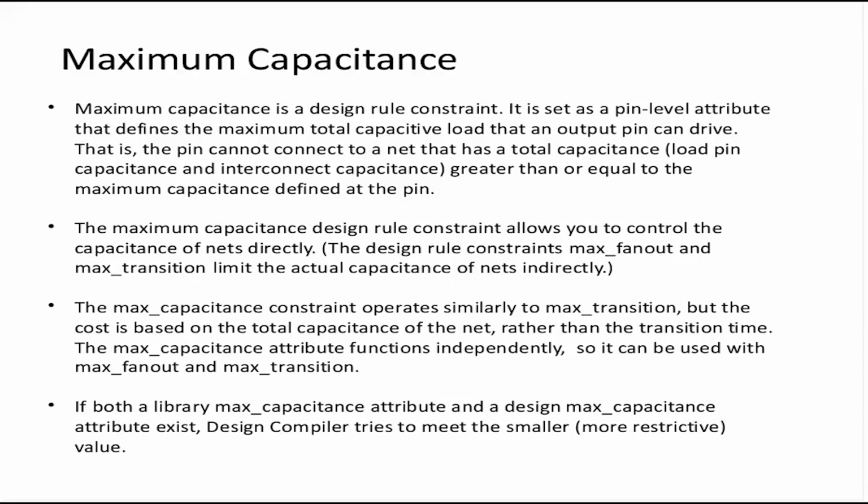So now what will happen is that the output pin of the driving gate will not be able to drive this long wire, and thus it will violate both the max cap and the max trans limit. Max cap will be violated at the output. So max cap is at the output. So again, I'll take the example of the lookup table. The inverter delay, for example, depends on the input transition at load, and that is why there is a max trans limit on the input. It depends on the output cap at the output pin. That's why max cap is a constraint defined at the output.